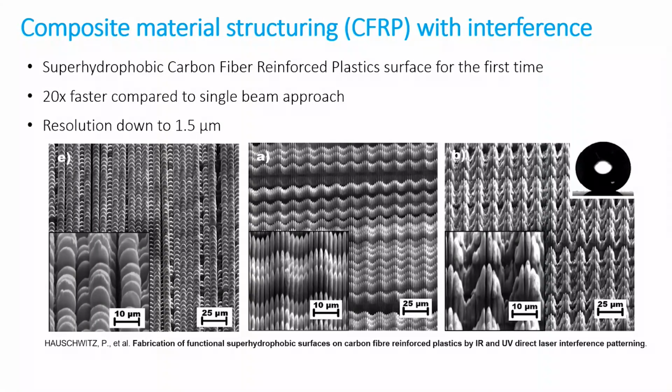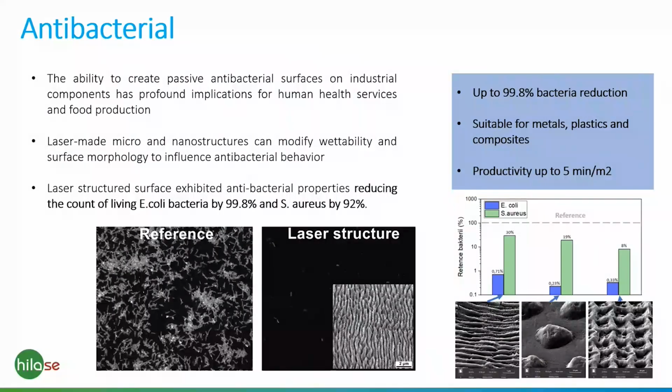This case study just shows that we don't need to use injection molding. In fact, we can structure a plastic part itself. In this case, it's plastics reinforced by carbon fibers. And as you can see, even direct laser structuring is possible down to 1 micrometer in resolution. Again, in this case, for superhydrophobic surfaces.